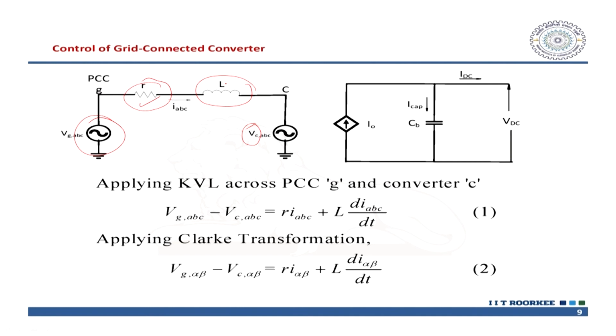So, what happened? We can write all these equations for the current source and the capacitor. In the case of this solar model, it fits quite well, because ultimately C dV/dt essentially gives you the I. So, I we can write as a voltage dependent current source.